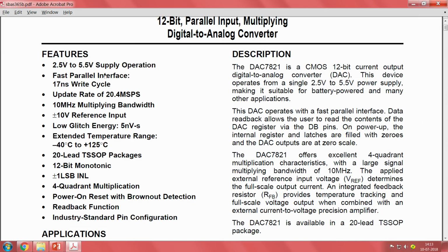What does that mean? It means that when we give the input to the IC, the data bits which need to be converted to analog, how much time does it take. The analog value that will be converted inside the IC would be stored in some buffer or an internal small memory, and that value, whatever analog value is there, will be written there. So, this is the time taken to convert the digital value. Next time you want to update the analog value, you have to latch on a new set of digital inputs. Until you latch it on, the analog value will not change.